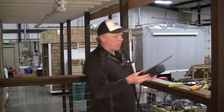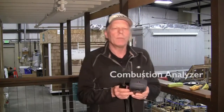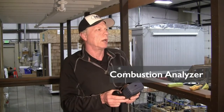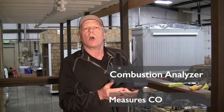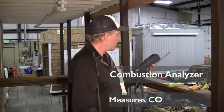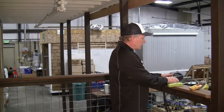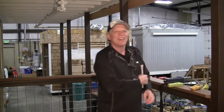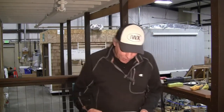And I'm starting up my combustion analyzer also. I use this device for measuring CO in my appliances. And so all they're asking for us to do in item number 1 is to prepare these for use. And we do these outside because outside is our baseline. And then we'll take them inside.